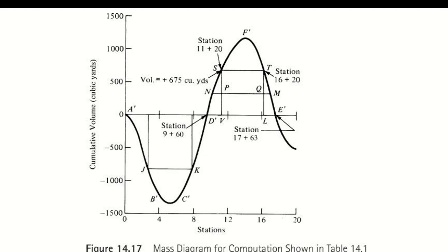Clear? Okay. So when I do this, I get the answer in cubic yards and stations both. This is summation. You can see there is no average here. I just added, right? This plus this. This is only addition. To get the average, I must divide by the total, right? So what is my total material? Okay. Clear? So this distance is what we call the weighted average distance.